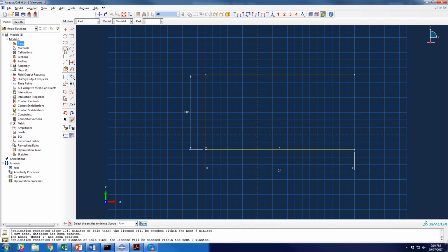create arcs. So we have a number of different ways we can create arcs, but I'm just going to use this one here, which creates an arc which is tangent. So if I click on this one, you can see I now have a tangent curve, and when I bring it around there, then it also forms tangent, so that's the right size.